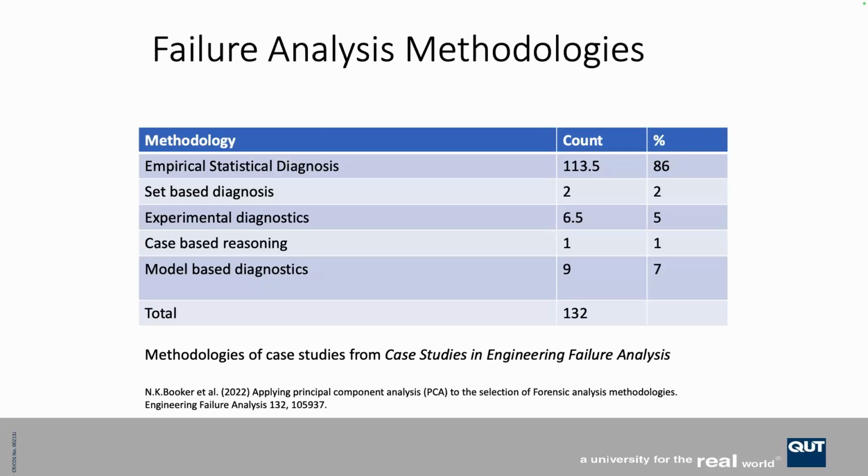In the set-based diagnosis, what you can do is look statistically at a whole lot of tests that examine the failure and gradually narrow down the tests to eventually describe what the failure is. Experimental diagnostics is usually where we try to absolutely simulate the failure, try to simulate exactly what happened in the process. Case-based reasoning is where we just look at different case studies and try to compare the cases to the failures. And model-based diagnostics is more about doing simulations, finite element analysis, and other types of simulations to try to understand the